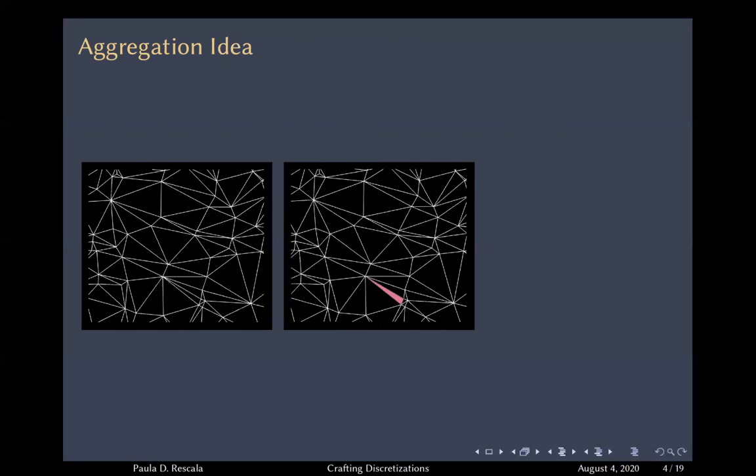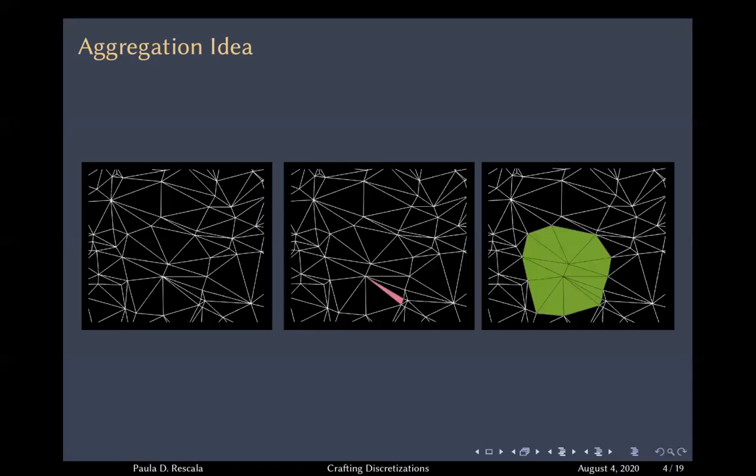And the goal is to aggregate different elements in the low quality mesh and get a cluster of high quality as shown here. Now this one was handmade, but the idea remains the same. This can be considered a high quality cluster since it is nearly convex. It is very compact and has a rather uniform moment of inertia over both axes.